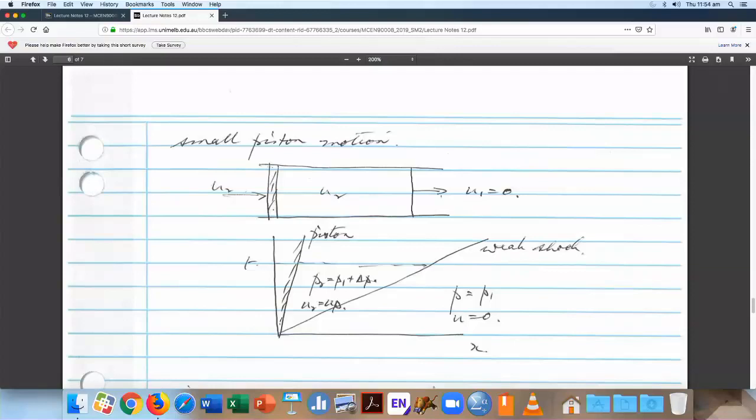I know that my diaphragm will distort, and I have waiting for it to distort a cutter, which is a very sharply edged, highly sharp steel cutter. So the diaphragm begins to distort, and suddenly it rests against this crucifix, which is a cutter, and of course it can't take the pressure and it ruptures.